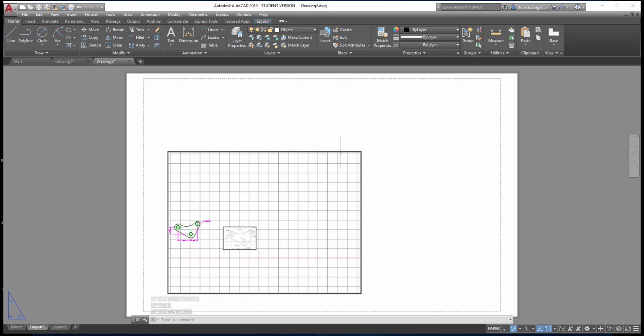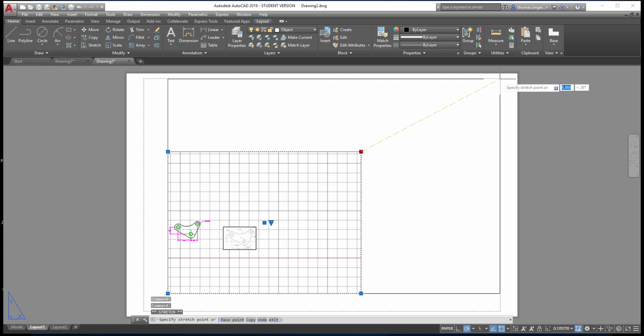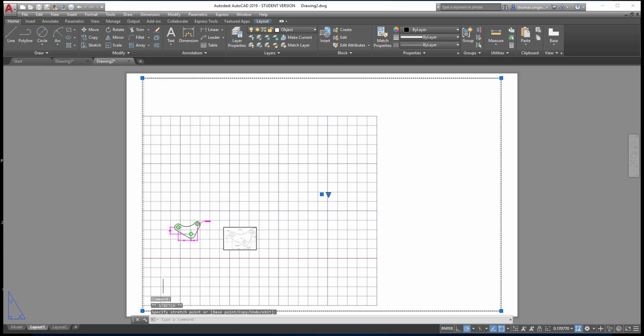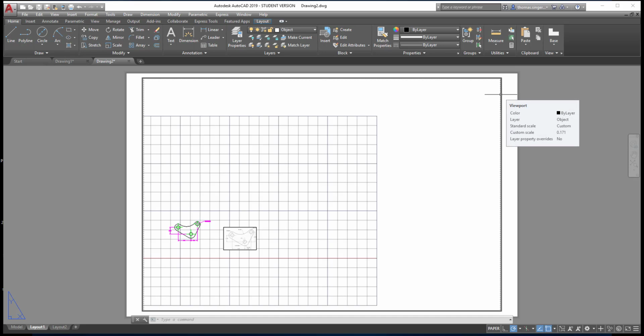And this is called a viewport. The viewport is actually the printable space, and so we need to expand the viewport out to the edges. Some actually go just outside of the scaled area. Why? Because the viewport will not print then. Those dark lines, if I hit the escape key, that viewport line will print unless you put it on a non-printing layer.